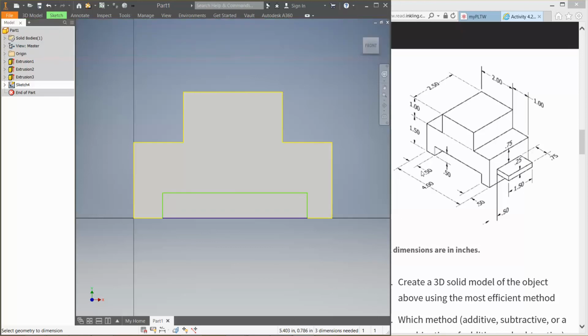So this tells me that this right here is a 1/2 inch. So I'm going to go from there to there. I'm going to change it to 0.5. And then from here to there, it is 0.5 already. I just lucked out. And then I know that the height is supposed to be 0.5. So I'm going to click there and there and make that be 0.5. I'm ready to extrude this.